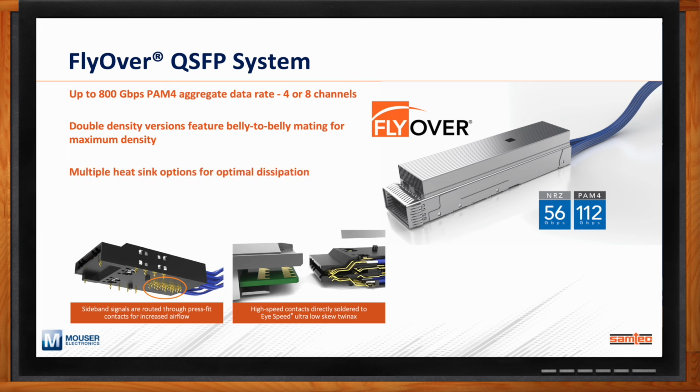Some of the listeners may ask, well, didn't you just say that FlyOver minimizes the need for heat across the system? And from the ASIC, yes, because we're removing retimers from the system. But each of the ports is going to have an active cable that's installed, whether that's optics or cable. Some of those ports have power of 15 to 25 watts. And when you put 36 of those on a 19-inch rack mount solution, you still have to get rid of the heat from the electronics within the cable on the front panel.